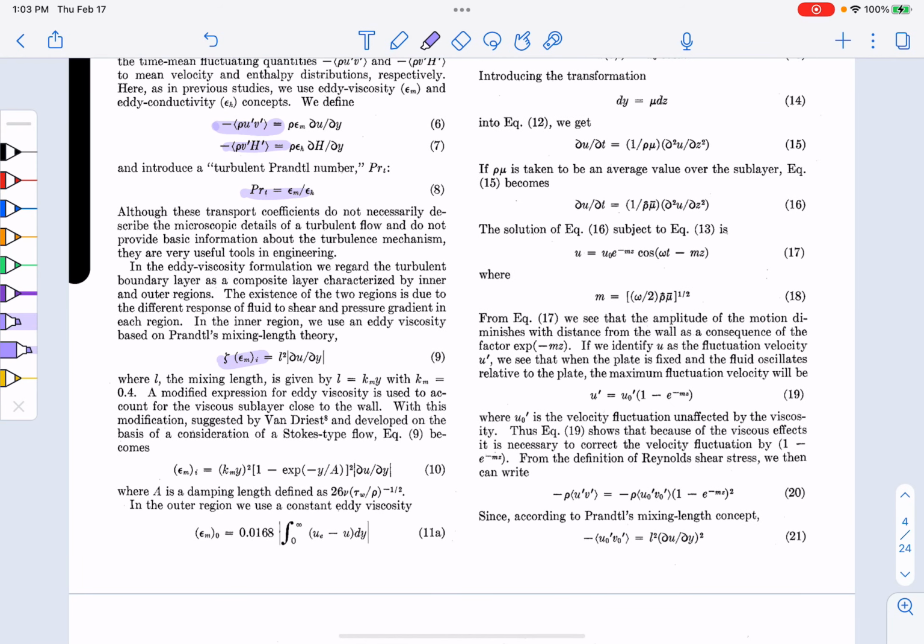And then he describes an inner and outer viscosity model. And this is probably one of the biggest problems with, or criticisms, I would say, of Cebeci's model, is that this term here really is some property of the boundary layer. And this term here, of course, is some sort of length scale model L. So right there it's algebraic because he's specifying 2 things really about the boundary layer. He's tracking boundary layer displacement thickness through the flow, and he's tracking a length scale explicitly. But you should expect at least one of those in an algebraic model.